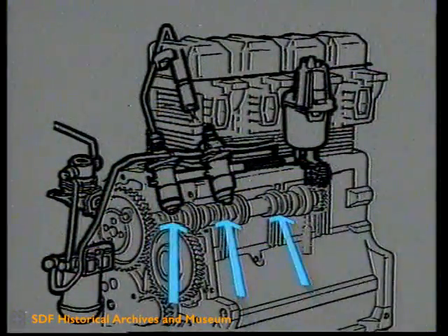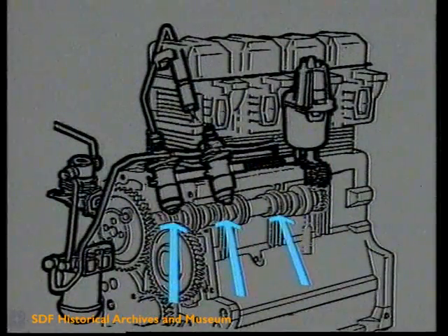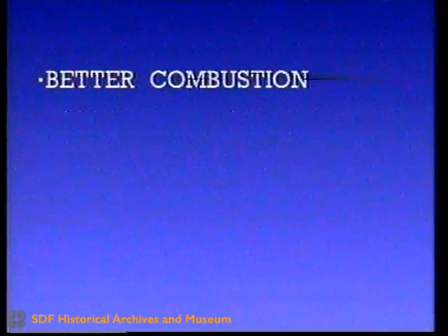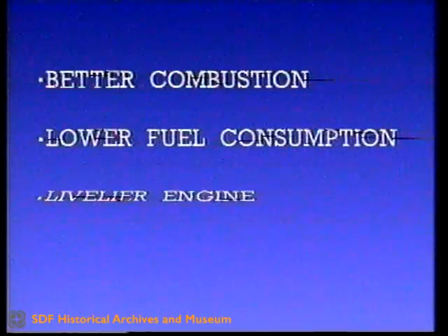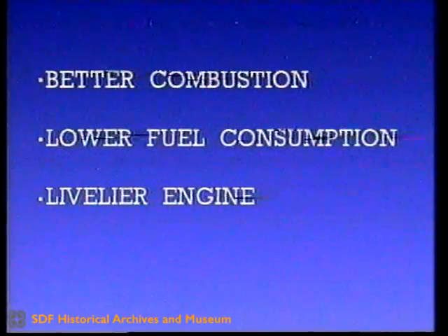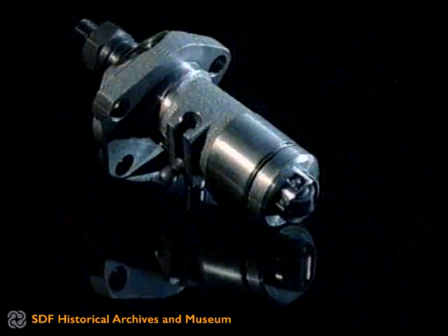Being actuated by large-size cams, the speed of injection is very high, and therefore injection times are very short, even at different engine speeds. Better combustion, more restricted fuel consumption, a livelier engine, less smoke emission, absence of supplementary filter, hence less sensitive to impurities contained in the fuel.